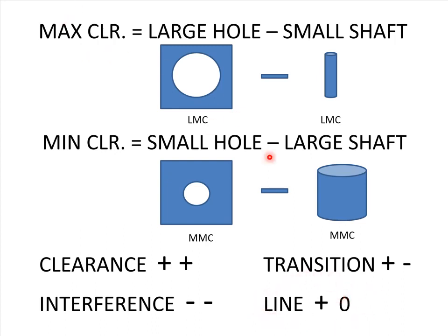So your maximum clearance will always be positive, always guaranteeing a clearance, or a perfect fit. The minimum clearance will be 0. Not a negative, not a positive, but 0. In other words, the diameter of the hole and the shaft are exactly the same. So this is once again hand to a glove. It's a perfect match. Either the shaft fits in perfectly because they have the same diameter, or the hole is just slightly larger, providing a little bit of wiggle room.